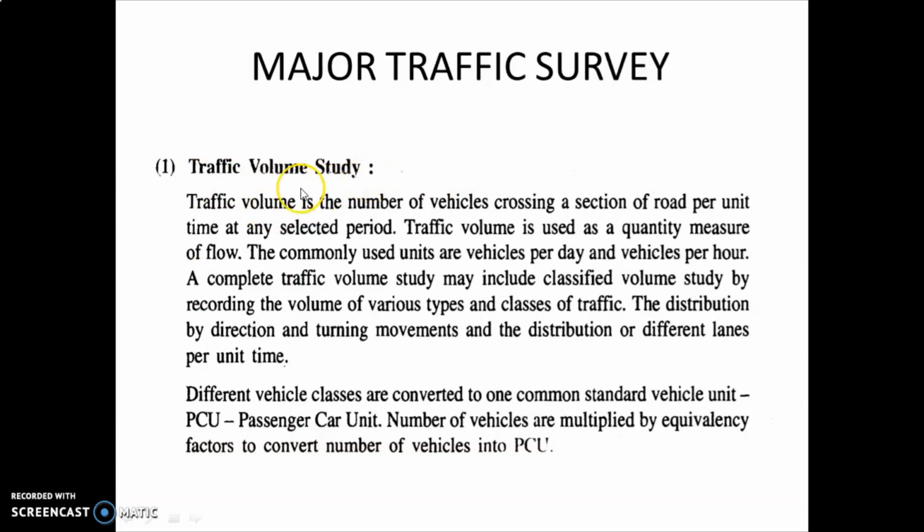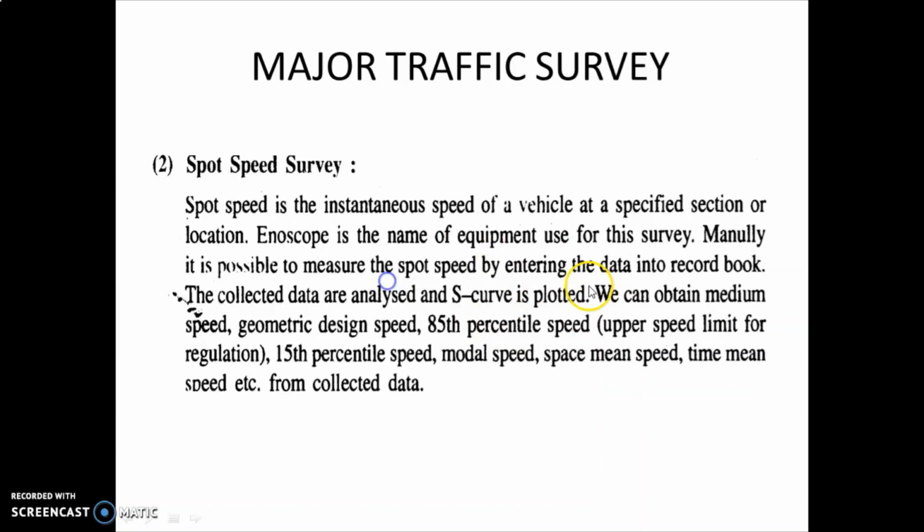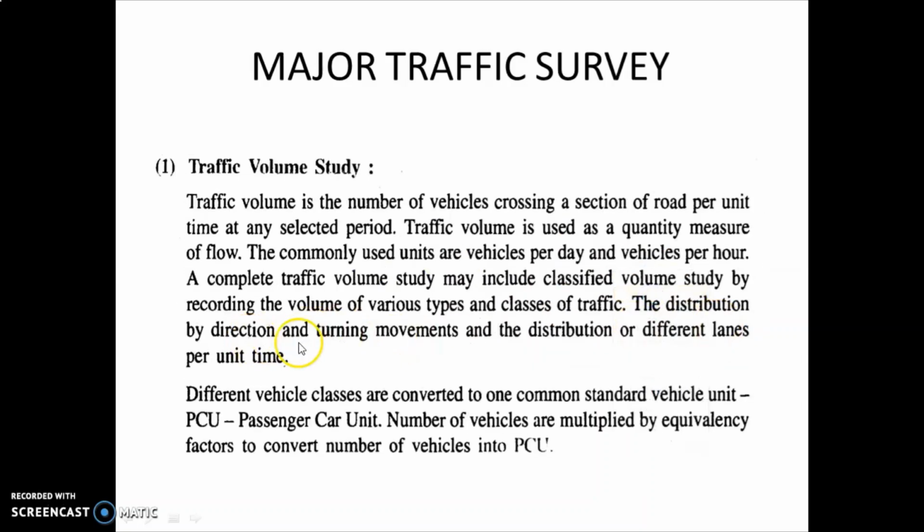So what is a traffic volume study? Traffic volume is the number of vehicles crossing a section of a road per unit time at any selected period. Traffic volume is used as a quantitative measure of flow. The commonly used units are vehicles per day and vehicles per hour. A complete traffic volume study may include a classified volume study, by recording the volume of various types and classes of traffic, the distribution by direction and turning movements, and the distribution of different lengths per unit time.